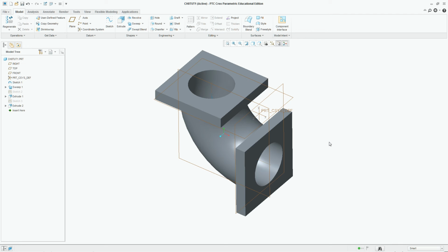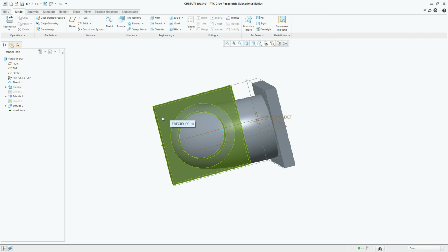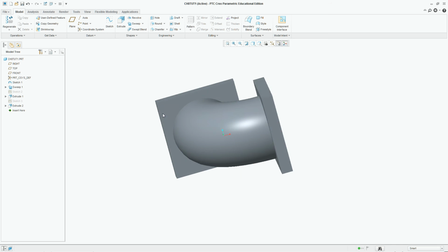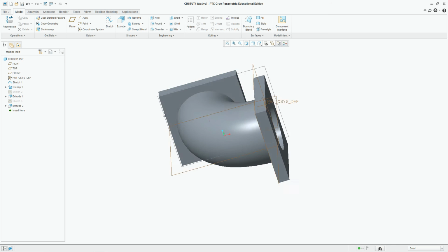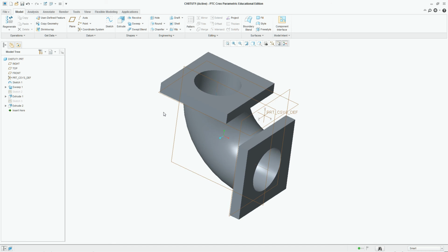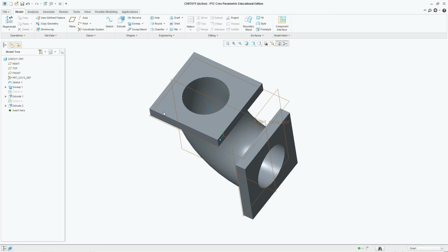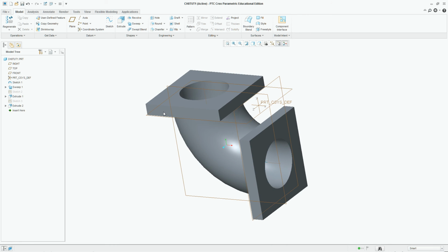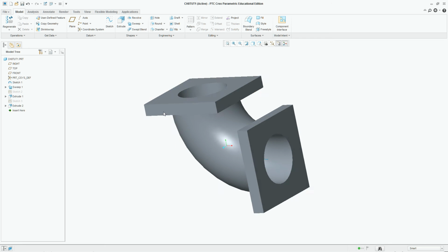So I can see that these are counterbored holes, but the counterbore is actually coming in from the back side. If you look very closely at figure 8-72 on page 8-31, on the right side view you can see the little bit of a counterbore that exists on those holes. It'll be a little bit more clear once I actually draw it on here, but just so that you're aware, it's not just a standard through hole, it has some additional information to it.